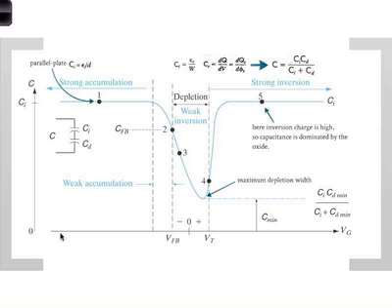Because it's always conducting, and because it's a majority carrier, they can respond really fast to changes in voltage, which means my dQ over dV, which is capacitance, will be very high. Capacitance is defined as how fast my charges respond for small changes in voltage. That's my instantaneous capacitance.